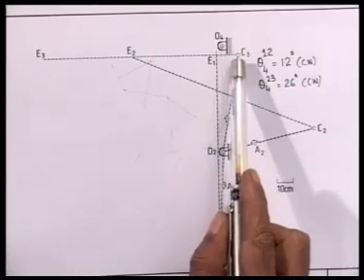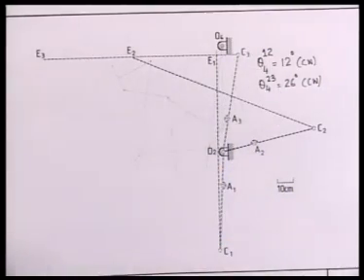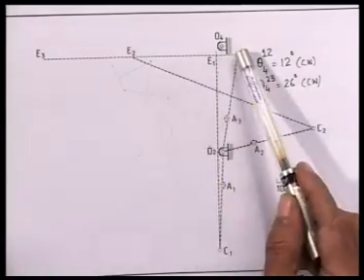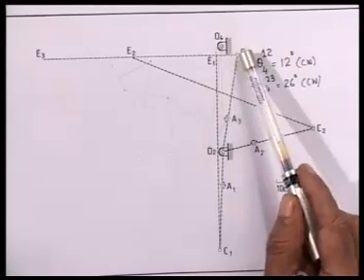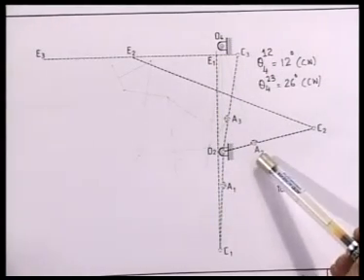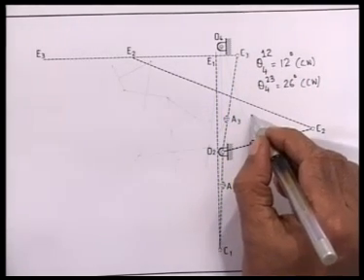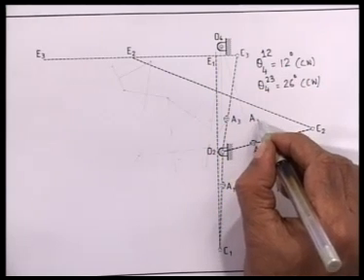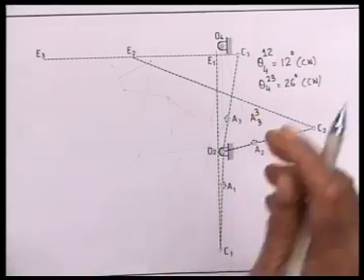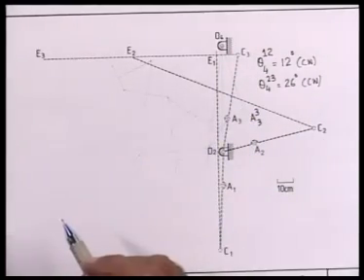Since we have to obtain the position of the hinge B at the 3rd configuration, that is B3, we hold link 4 fixed at its 3rd configuration and make a kinematic inversion and determine the inverted positions of A1 and A2. A3 is nothing but A33, because we are holding the link 4, that is O4B, fixed at its third configuration.